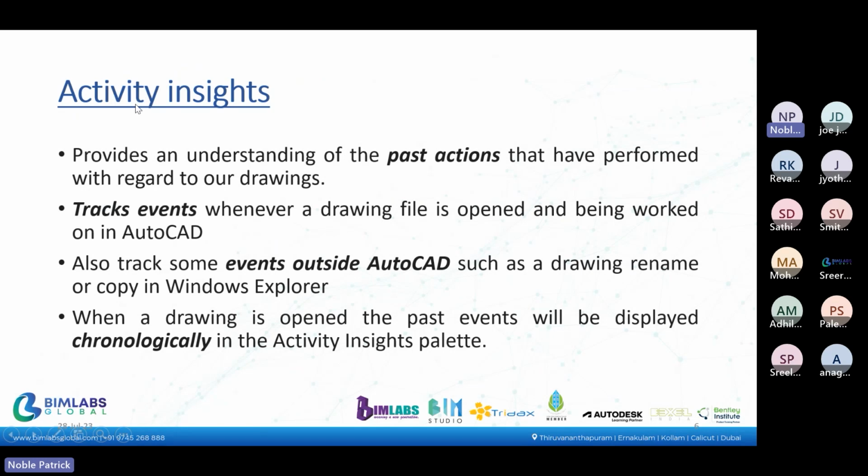In the View tab, we can get a new menu or new tab called Activity Insights, which provides an understanding of the past actions that have been performed with regard to a drawing. We can track the entire functions that we have performed, whether we copied, pasted, just opened a drawing, deleted a drawing, or edited a drawing.